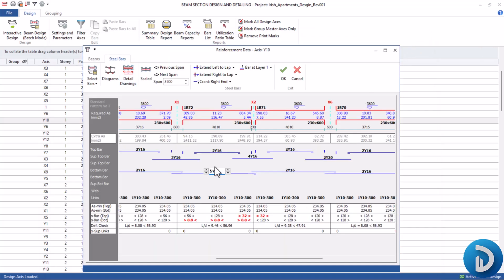If we have situations like this, what we can do is create a different layer of reinforcement which is separate from the first layer. So we have what, bottom bar here, and if you observe this part, we also have what, another layer of bottom bar. So we can come here to this second part and reduce this, and since five numbers of Y25 is required, we can reduce this to three numbers, come to the second layer and take this what to two numbers of what, Y25.